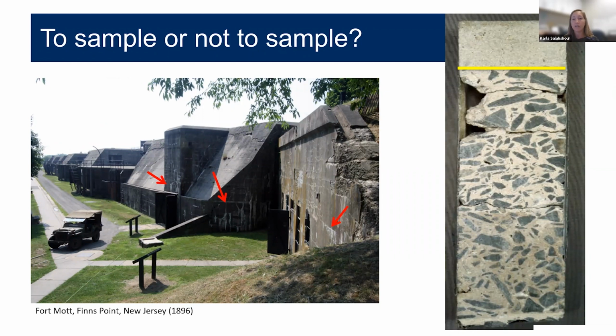And today we don't typically use this two-layer construction specifically to achieve freeze-thaw durability. We have technology and admixtures now. So now we simply just add air-entraining admixture and lower our water to cement ratio to get that durability. Although I am biased, I work in the laboratory, I do think samples can be instructive, but only if they're carefully selected and extracted. We also need to give credence to the historic aspect of some of these projects and pay careful attention to where the samples are extracted to not alter a significant component or fabric of the structure. So that leads to more discussion on samples.